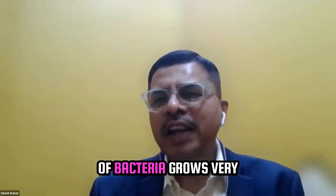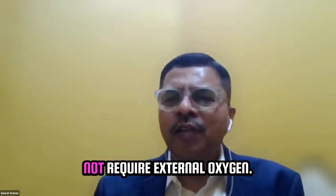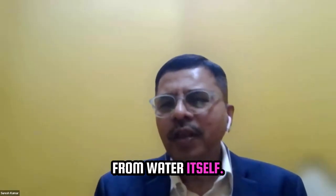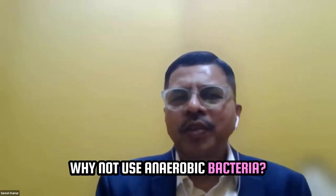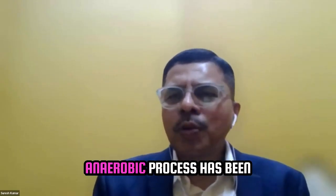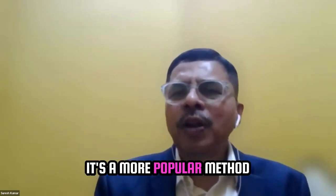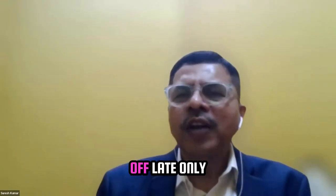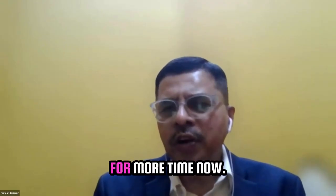So a different type of bacteria grows. We call it anaerobic bacteria. This anaerobic bacteria does not require external oxygen. It would probably take oxygen from water itself. Now, what is the difference? Why not use anaerobic bacteria? Every septic tank uses anaerobic bacteria. Anaerobic process has been there traditionally. It's a more popular method of sewage treatment compared to aerobic. Aerobic has been in use of late, only in the last 70-100 years. Anaerobic has been there for more time.